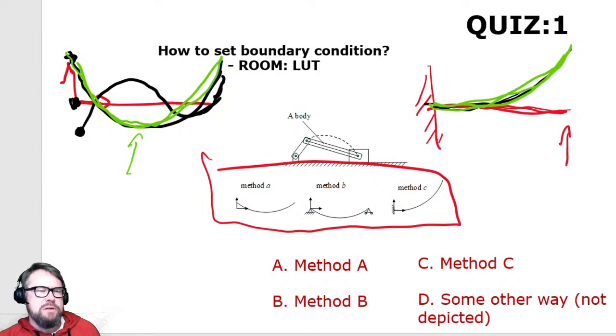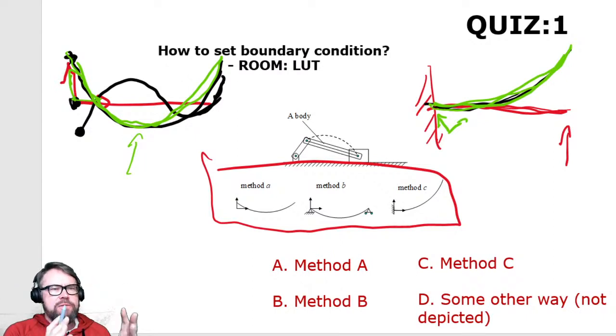So where will the body reference coordinate system be in this case? Well, it will be here, because look at where it is here. So it's no longer attached to the point, but will be moving. It will be floating with the body. And this is where the title floating frame of reference formulation comes from, because you can use modes that have no boundary condition but are free modes. And in the case of free modes, the reference coordinate system is no longer attached to any material point.